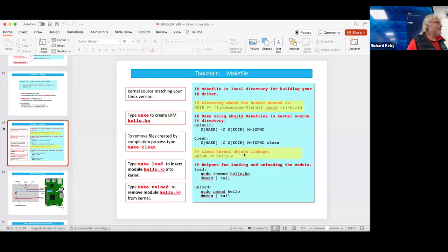What you find with Linux is they try and make driver writing a bit easier each year. So they already have a whole library. Instead of you having to get really low level into all these register addresses, there's a whole bunch of GPIO access functions. There's a GPIO core layer that Linux provides, so you can use that instead if you want to. And they have fairly common bits of hardware that it can be used for. So that makes life a bit easier.